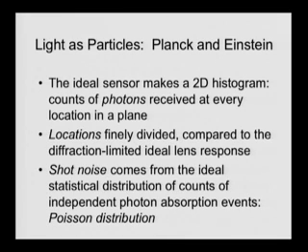Because when you have an image sensor in a camera, even if it's a piece of film with a bunch of little crystals of silver halide or something, it basically works by discrete light absorption events, photons, little packets of energy that cause some change to happen in a crystal. In a silicon solid-state image sensor, we can almost count the photons that come in by counting the electrons that those photons generate. That's what the ideal sensor does.